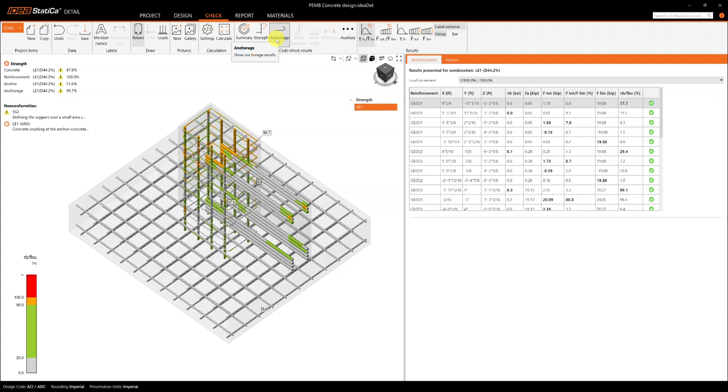So instead of calculating development length, we are using the actual bond stress. The development length formulas were created so that, instead of looking at the stresses, you can look at a length, right? So it was kind of transforming the bond stresses to a length. So in this case, we are calculating the actual bond stresses of the reinforcement.